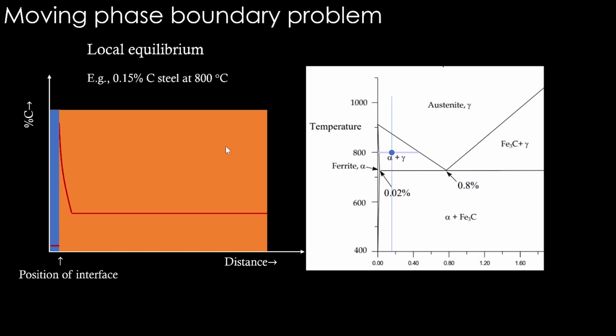Okay, so in this regard, how do we track, how do we conclude the simulation is over? Position of the interface we are going to track. Let's say it grows up to some region, and beyond that the ferrite cannot grow, because that's what the lever rule tells you. It says this is how much ferrite can form. Beyond that, with respect to time, the position of the interface will be constant, and that's how we will track it.